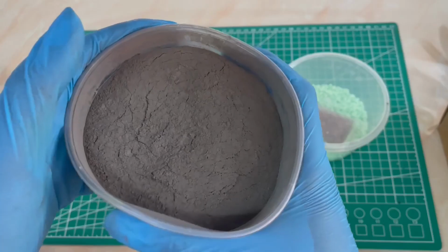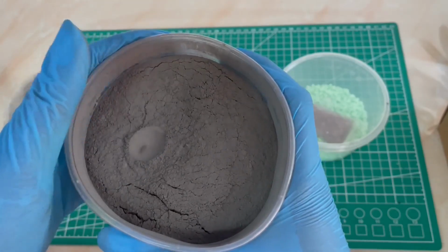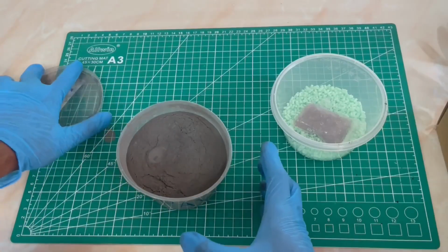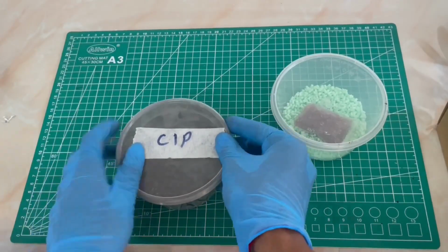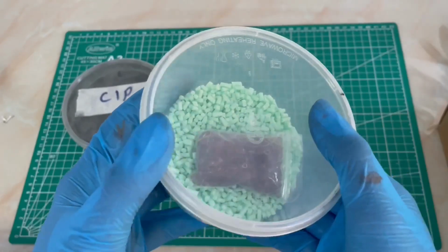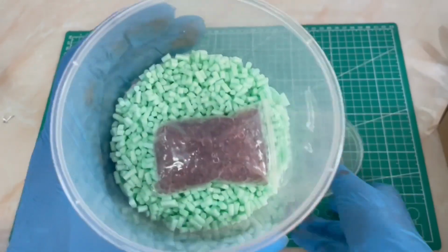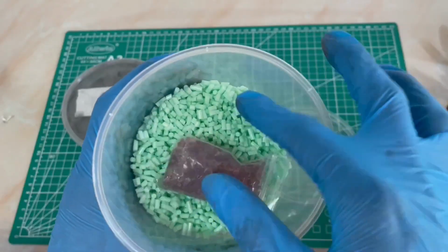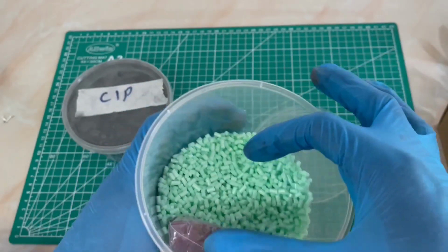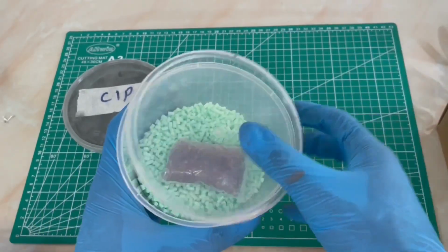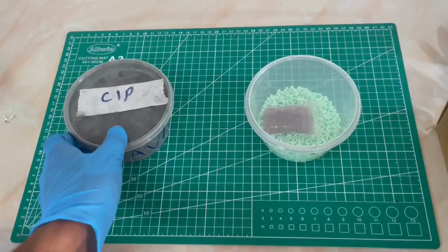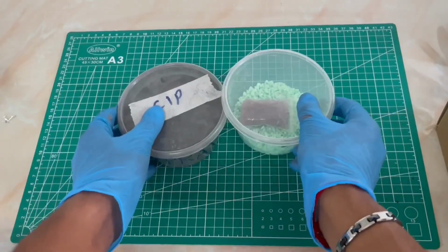The next material needed will be the polymer, or in this case, we are using thermoplastic elastomer, also known as TPE. TPE is used to induce flexible properties to the filament, making the filament more flexible so that it contributes to more types of applications. So in this case, I am showing you a thermoplastic rubber. The fabricated filament was using thermoplastic polyurethane. So any types of thermoplastic polymers can be used to fabricate this magnetic filament.